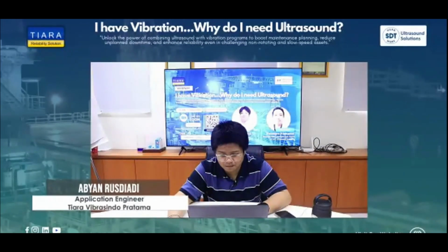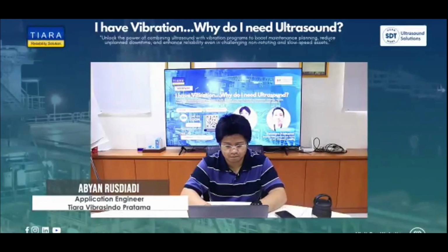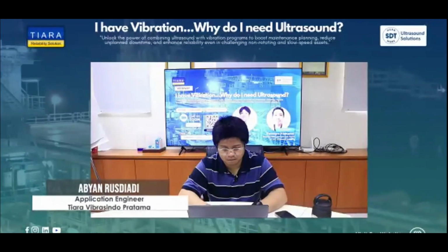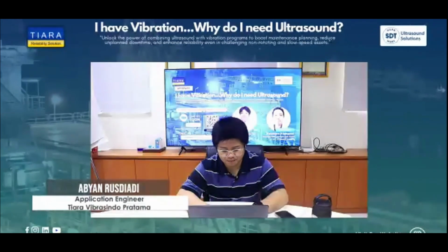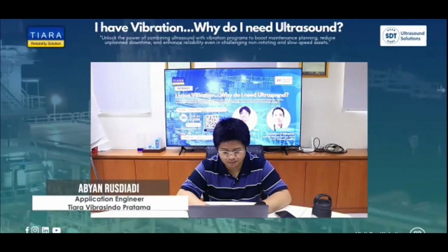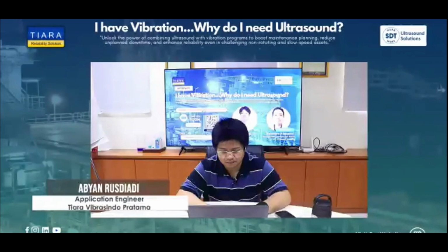If we talk about vibration and sound, I do vibration analysis also. If I go to measure a machine like a motor or a pump, I have vibration certification, Cat 1, Cat 2, Cat 3 or 4. The first thing that I know is that the type of machine should be a rotating machine, because vibration can measure only rotating machines.